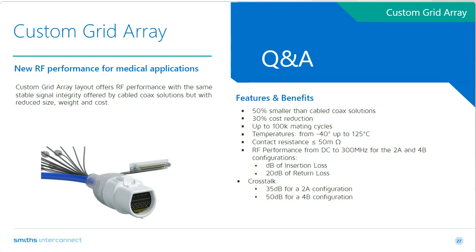Yeah, there are two primary ways to terminate this interconnect solution. For one, you can terminate with PCBs, and this would probably be like a rigid flex rigid PCB, where one would connect the contacts to the rigid side of the PCB and wires to the other rigid side of this PCB. This would give the benefit of being convenient and user-friendly during assembly, and it's also reworkable. The downside would be there would be some material increase in cost, and there would also be a slight impact to the performance, the digital and analog signals across the PCB.